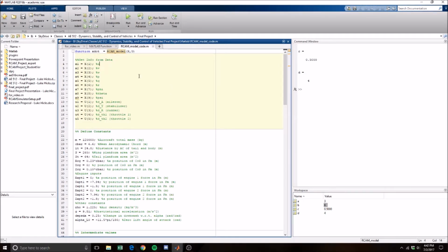What this does is it takes control inputs in. So I tell it where my aileron is at, where my tail is at, the stabilizer, where my rudder is at, and what my throttles are. And at discrete time steps, for example a half second, it will compute the plane's states, which are defined here: its angle, its speed, how much it's rotating, that sort of stuff. It'll keep computing, and I'll keep getting inputs. So it loops like that, and I can compute the plane.